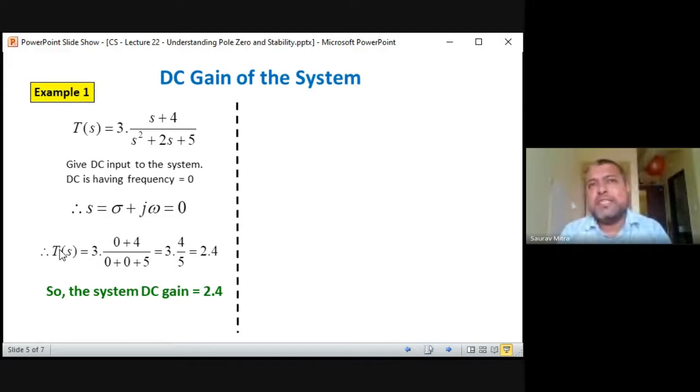So what is Fourier series? I give you a square wave signal and ask you to represent it by means of sine and cosine, because sine and cosine form a basis function. What is meant by basis function? A basis function is a set of signals by which you can represent any other signal. All this has come out of research, and research has shown that sine and cosine are a set of basis functions by which you can represent almost any composite signal of the world. But the signal has to be periodic and continuous; only then can you represent it by means of the basis functions given by sine and cosine.